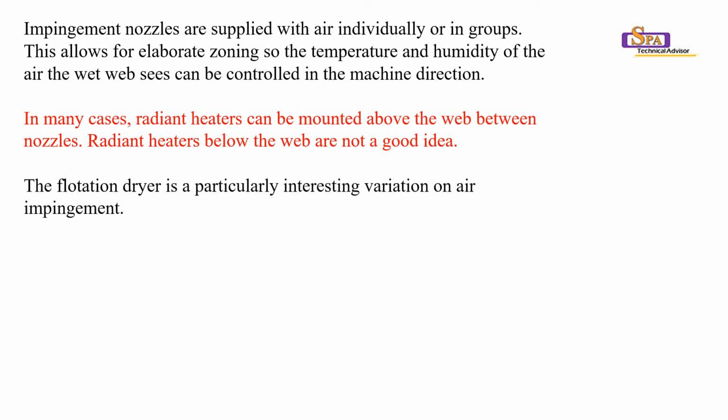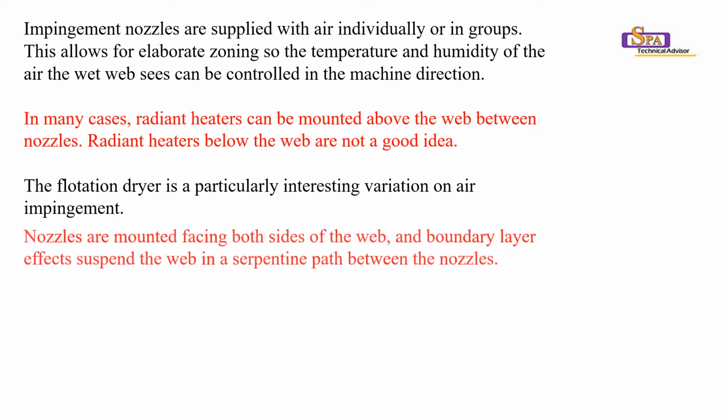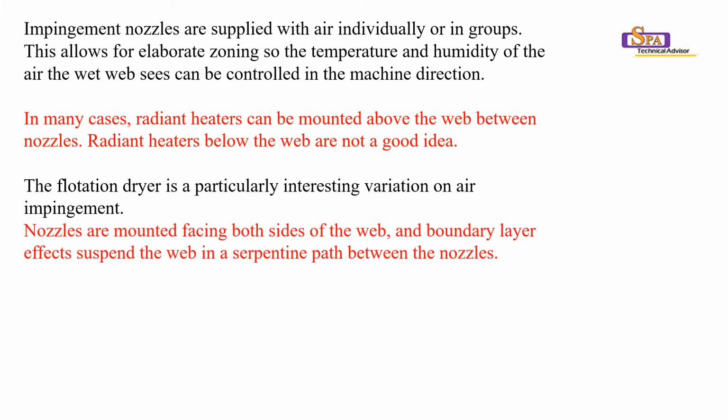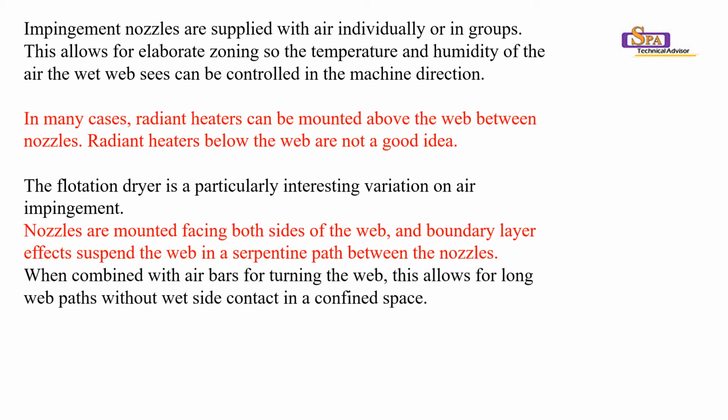The flotation dryer is a particularly interesting variation on the air impingement. Nozzles are mounted facing both sides of the web and boundary layer effects suspend the web in a particular path between the nozzles.